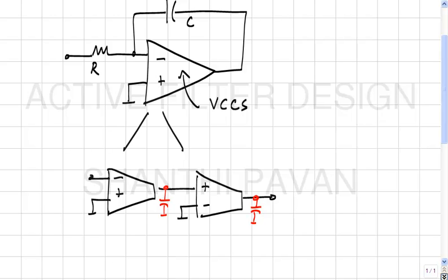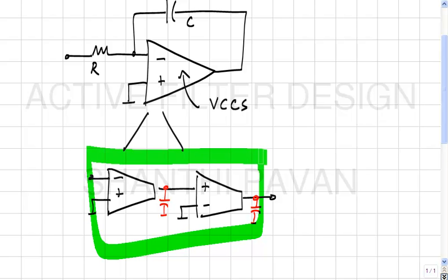And so clearly it is apparent that at low frequency you essentially get an infinite short circuit transconductance. The equivalent Norton current source at the output of this transconductor is simply GM1 times RO1, which ideally is infinite, multiplied by GM2. That is the short circuit current which flows into the output, and that definitely is much larger than what you would get with a single stage transconductor, unless the transconductor happens to be infinite, right. At least you see the motivation for doing this.